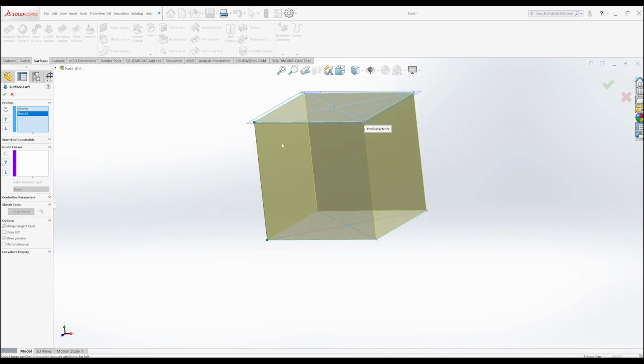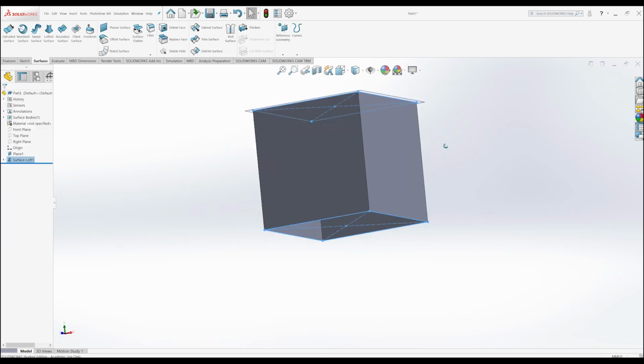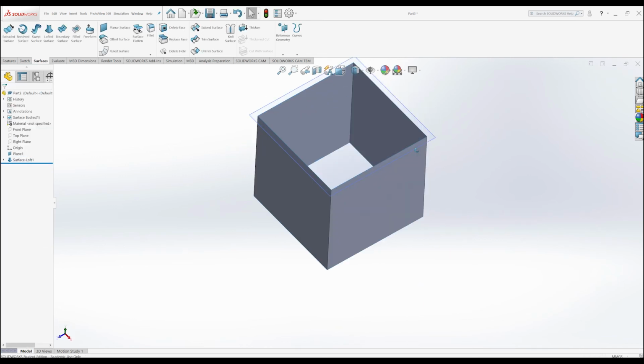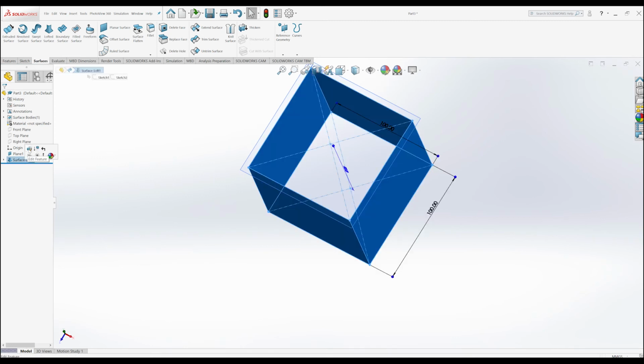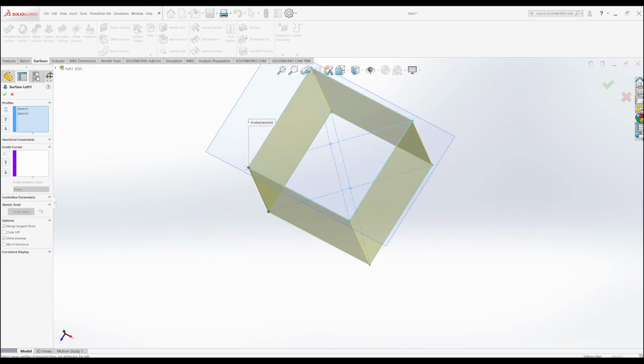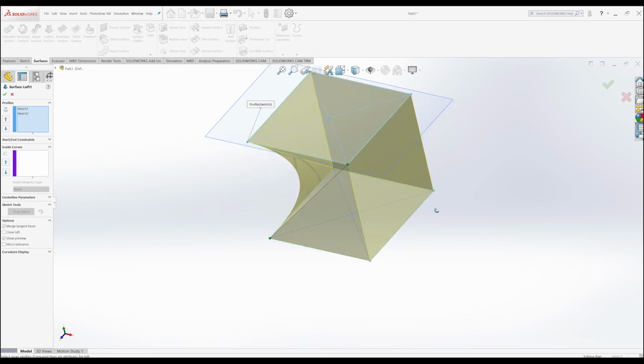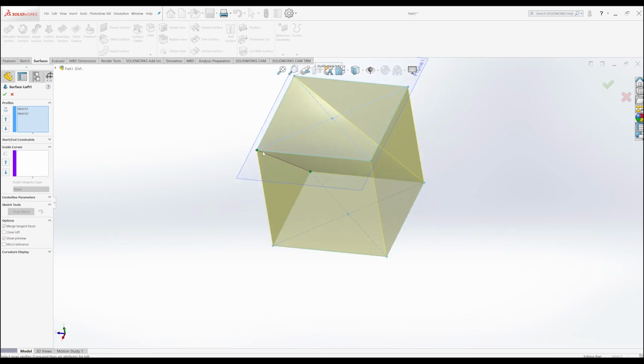If you want to add the curve, because if we just green tick on that, you've still got the hollow, just longer shape. If we want to add that curve, I can go back in and do edit feature, and you can just grab hold of one of these green circles and move them across one. So if I move it to there, you then get your curve appearing.